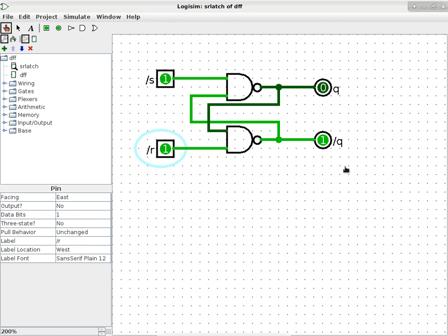Later on when we looked it up, the new date code indicated that they changed the die process. They changed the transistor size from one size to a smaller size, and that changed the timing enough so that the race condition now favors the other side, the wrong side, so to speak. So the software issue happens. It took me 3 days to find out which 2 instructions were reversed and responsible for that particular bug. Wow. Yep. I'm not sure how much of this you understand, because there's a lot of technicality in it. But the whole point is race conditions are important. They happen in real life, and they can have a major impact on devices.